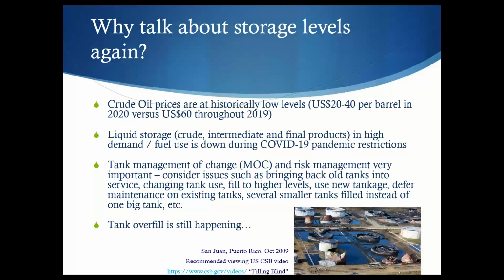The other thing is considering the issues around management of change. It's very important. Bringing back old tanks into service. There's probably a number of old tanks that have been brought back into service over the last year or so, and you're filling them probably to higher levels than you were before, sailing closer to the wind, if you like, in terms of the trip levels or the alarm levels. But every time you bring something back into service, you need to do a proper management of change on it. And some of those issues, I'll talk about today.